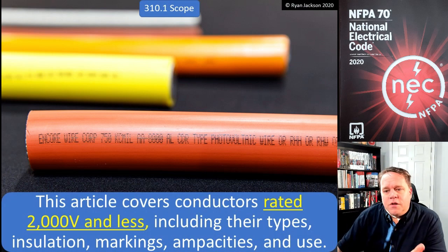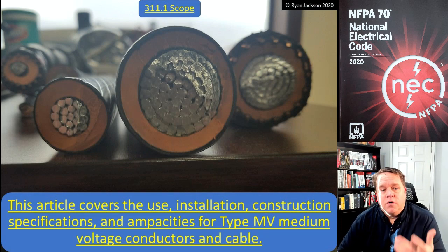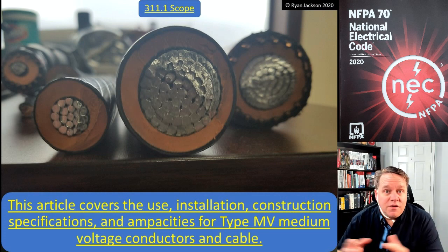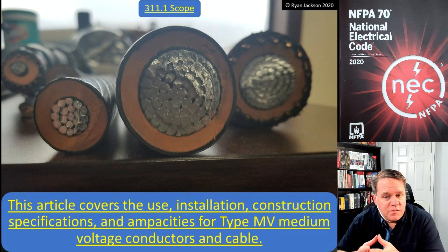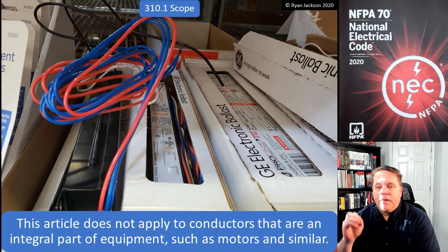All right, so we limited the scope to 2000 volts and less. What do we do with medium voltage conductors and cables? Well, those are now in Article 311. So if conductors like these are your cup of tea, well, great. It's in Article 311. So this article covers the use, installation, construction specs, and ampacities for type MV medium voltage conductors and cable. All right, so that was kind of a change made in Article 310 in the 2020.